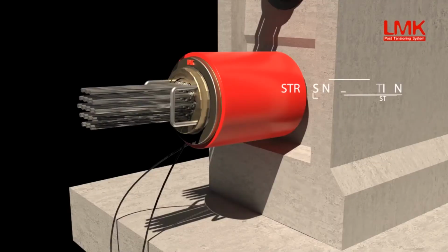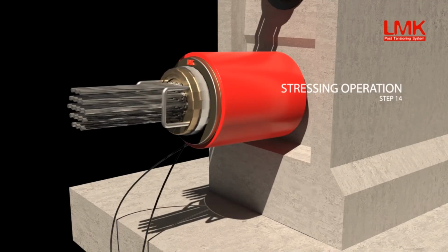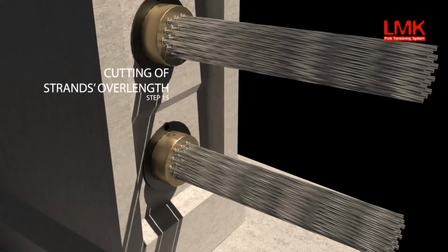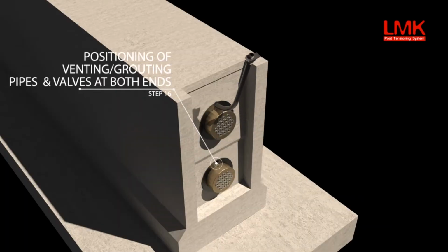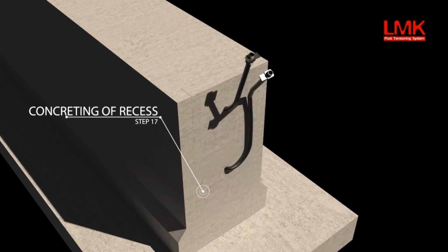The compressive force is usually provided by tensioned steel wires or strands which are anchored against the concrete, and since the stress in this steel is not an important factor in the behavior of the beam, but merely a means of applying the appropriate force, full advantage may be taken of very high-strength steels.